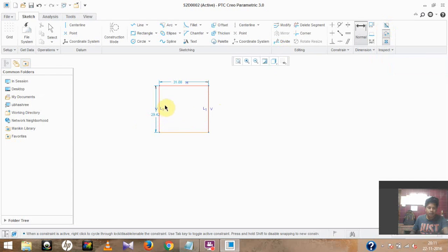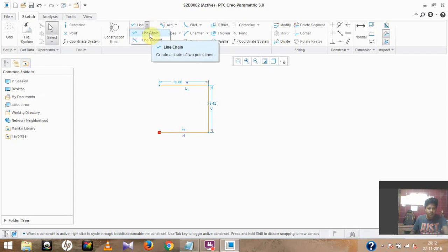It is one of the efficient options. By deleting this first line, we can see whether there is any overlapping or not. If you want to delete, just select that line and press delete. As you can see, while deleting the first line, I do not have other lines, which shows that we do not have any overlapping line over here.